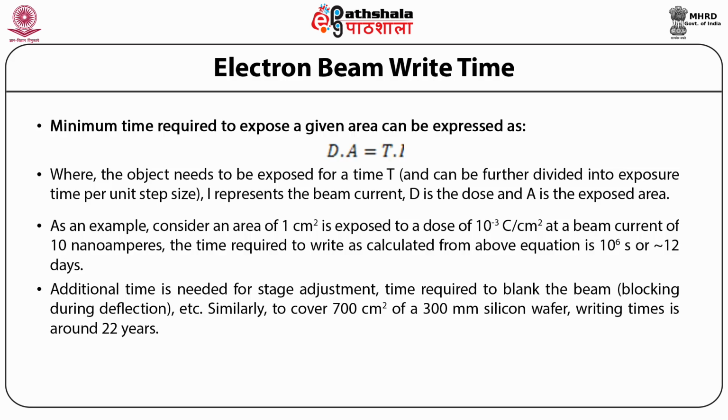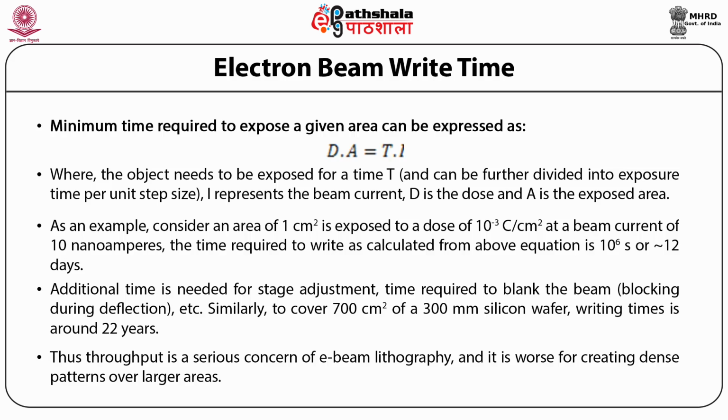Similarly, to cover 700 centimeter square of a 300 mm silicon wafer, the writing time is around 22 years. Thus, throughput is a serious concern of e-beam lithography, and it is worse for creating dense patterns over larger areas. This seriously precludes any commercial scale production using this technique.